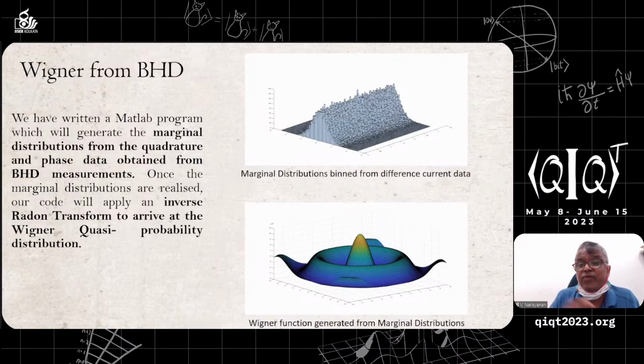The detectors, which are the photodetectors used here, are not single-photon detectors. A photodiode will do, but it should have a large quantum efficiency, as close to 80 to 90% as possible. Sometimes one uses PIN photodiodes also. The photodiodes are very, very cheap, and if someone is interested, I can give some information related to that.